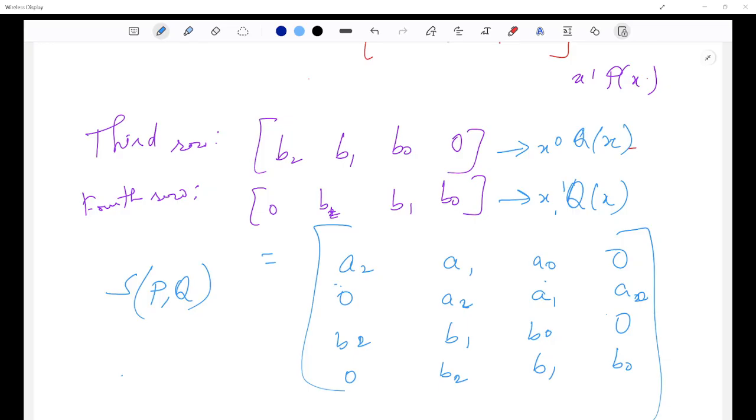So in inverse kinematics, trigonometric equations are also derived from tangent half angle substitution, which I already said, and in the lecture it is given in a very systematic way. So it leads to polynomial equations. Here we can eliminate one variable, and the resultant is basically a determinant of the Sylvester matrix. So this matrix is not abstract math; it is a tool for inverse kinematic solvability, right?